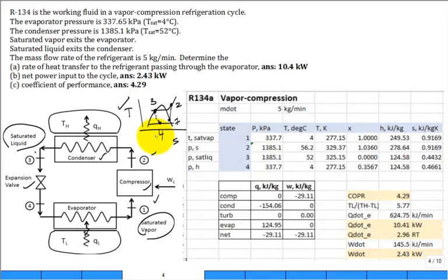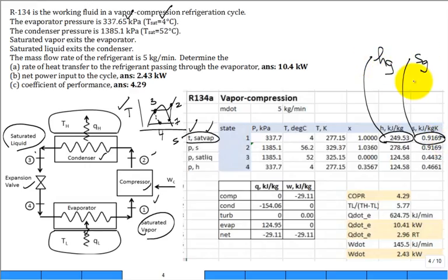All right. We then put little notes like, oh, it's state 1, it's saturated vapor. And either you know the temperature or the pressure. Both of them are given. There's the pressure of the evaporator, there's the temperature of the evaporator. Okay. And then you can just get, what is this H right here? If it's saturated vapor, it's Hg. And then this S, Sg, and the quality is 1. All right. Then we go to state 2.